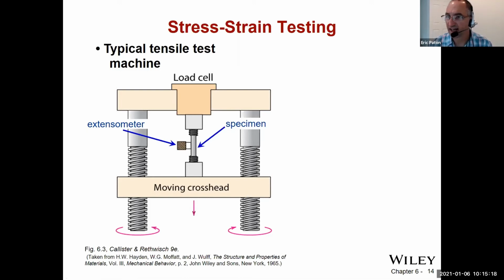The Instron has a very sensitive detector on the moving crosshead, and it also has a very bulky mechanical structure of the crosshead and the claws, so that you get very, very little deflection within the mechanics of the moving crosshead, and you can negate any deflection occurring in the crosshead from the total amount of deflection. So all of the deflection is hopefully occurring just within your material itself.